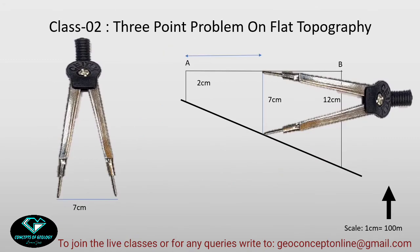Now, as this was a special case, we have found the 700 meter contour line very easily, but to do that in a perfect way we need to use this geometric method. I have to draw the AB line first, like this one. This is the AB line. Here I will draw the 200 meter borehole, that means 2 centimeter according to my map scale. Here I will draw the 1200 meter borehole, that means a 12 centimeter line needs to be drawn. I will join these 2 points because both boreholes have encountered the coal seam. So this will be the appearance of the coal seam along the AB profile.